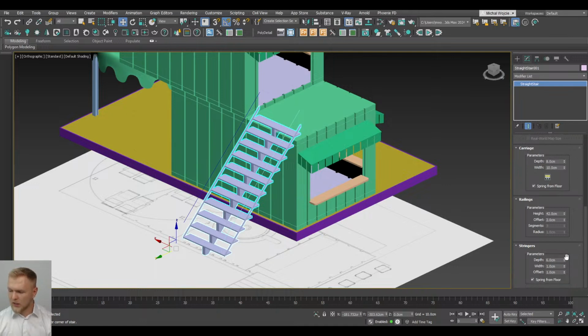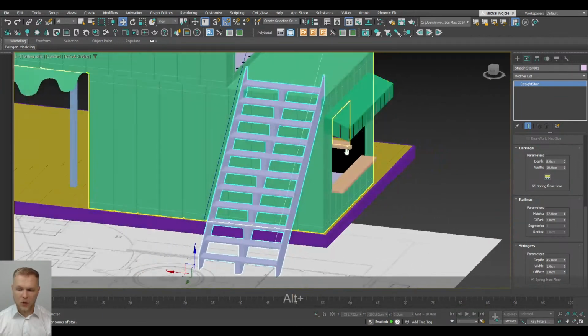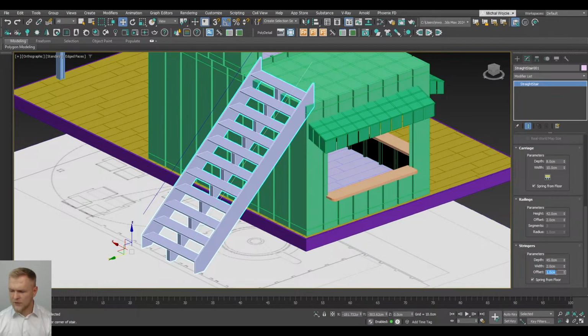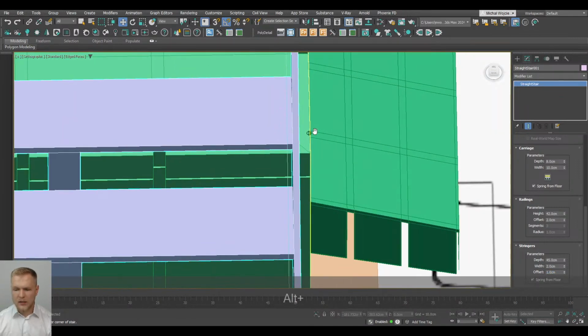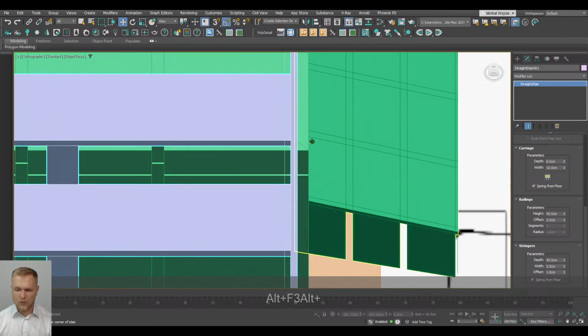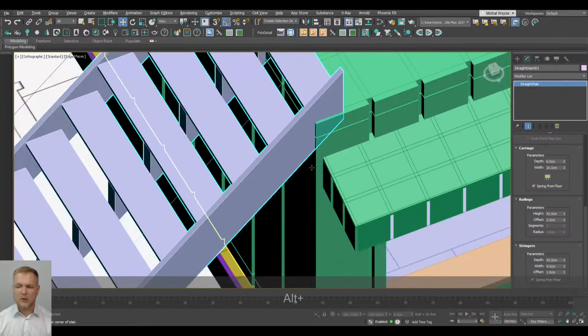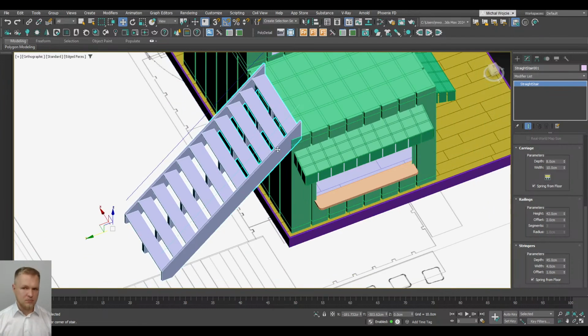Now the stringers, we need way bigger depth, way bigger, so it's going to cut into our object as we go. This is going to be also very helpful because now I need to go width of 2 and offset of 1. So in this case, I want this to be a little bit outside of my staircase. So we want to add at least that much thickness. 4 is going to be fantastic because it's going to be easier to add all the railings and whatnot. So let's go for that.